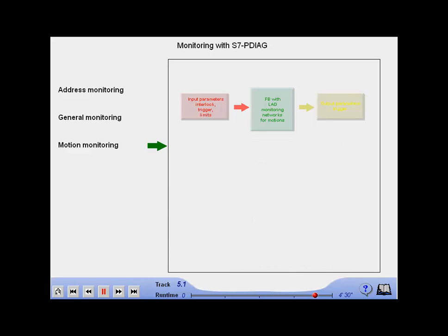The standardized data structures make it possible to incorporate ready-made HMI masks, such as the manual operation mask, without having to do any programming. This option for generating standardized multiple-use monitoring blocks, which also adapt their instance-specific message text automatically, is a great potential for streamlining in engineering.